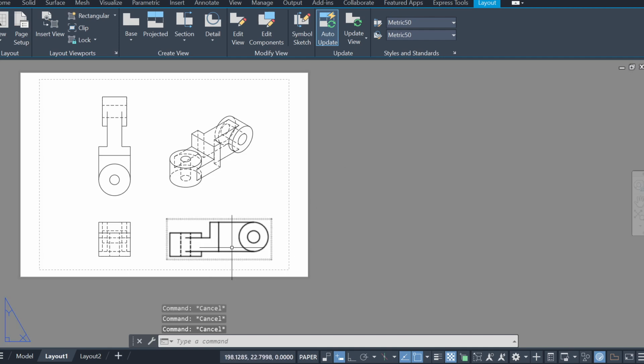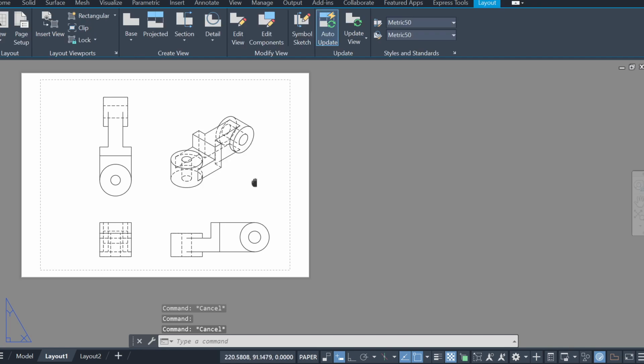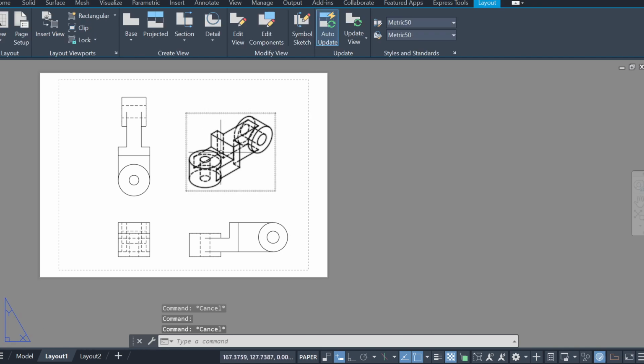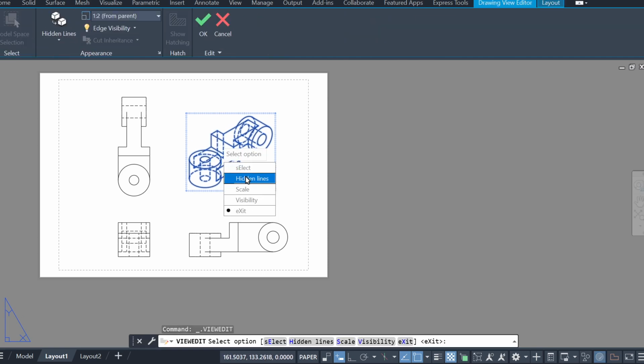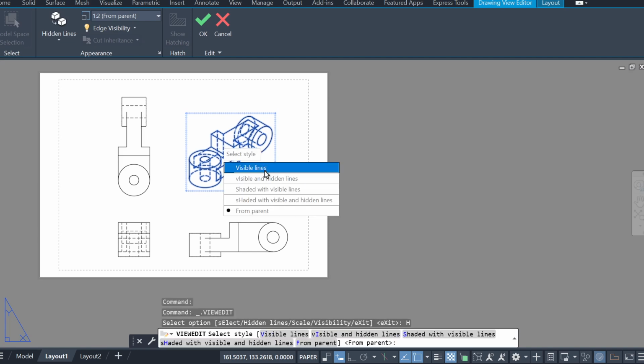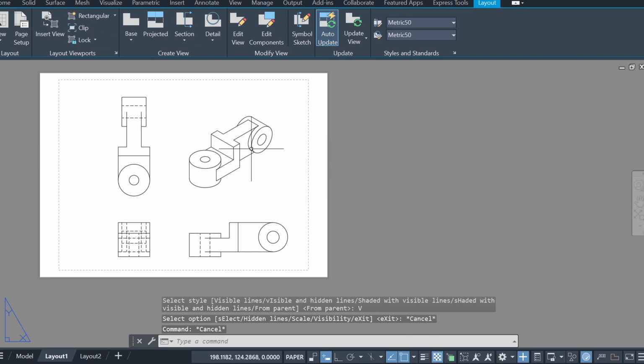Yan. And it will be okay na siya. And it already gives you the hidden lines, no? Parang available niya siya sa atin. This one, if you look at it, parang this is the isometric view. Hindi natin gusto na may hidden lines dito, no? So what we can do is we can double click, then lalabas ito, hidden lines, and what we want is visible lines lang dapat. Parang something like that, and that will be a better na view, no? Okay? So that's how you create the multi-view.